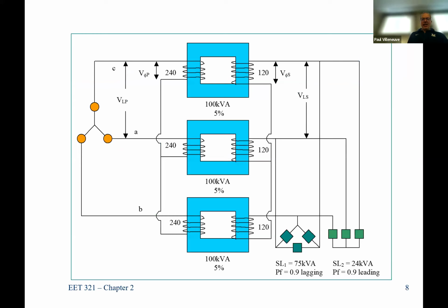So here is a grounded Y. So here's our power supply. Actually, it's not even grounded. This is the incoming power supply, and we show it as a Y connected one, but it could be delta. And how do I know this is a Y? Because if these are my dotted windings, you notice the non-dotted windings all connect to a common point. So I have three physically separate transformers, those single phase pad mounted or pole mounted transformers. You can buy three independent ones, and then you could wire them up and you could get delta Y, Y delta, whatever you want.